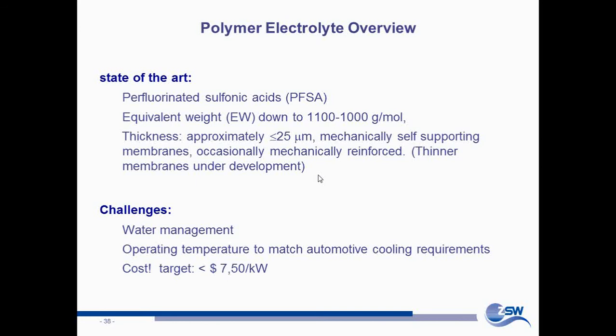So the higher you drive a fuel cell, the more of the chemical energy of hydrogen is transferred into heat. If you drive a fuel cell to higher current densities, you get lower voltage. Automatically, you get more heat. Therefore, you need to remove that heat from the system.